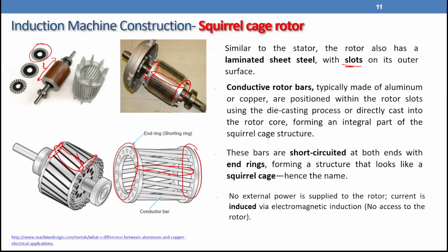In the classroom, students always ask a good question: why are the rotor bars skewed? This is a good question, but that one is a big story that needs a different analysis. Quickly, we can say here that skewed bars are deliberate. We need to reduce the cogging torque, smooth the interaction with the field, and minimize magnetic locking. That also reduces harmonics and improves starting performance. So in summary, the skew is there to improve the performance and avoid any cogging torque at starting. But there is analysis we can add to find the skew angle and so on.